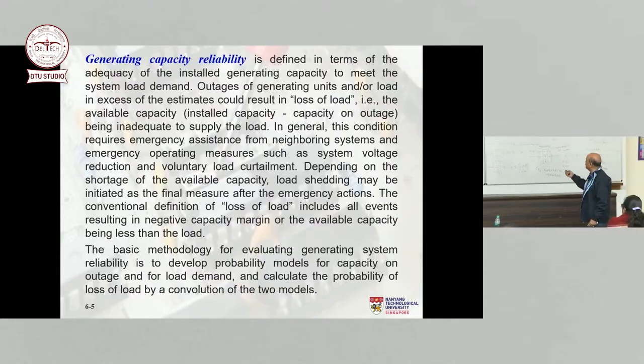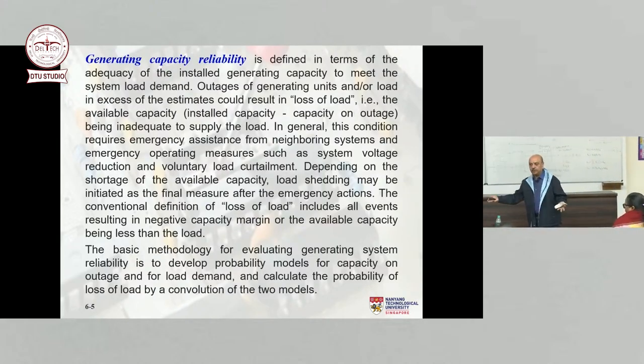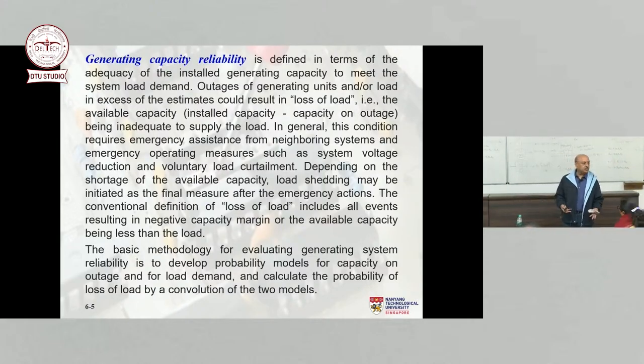But whenever there is a loss of load, then none of this works, because you have exhausted all the possibilities, including willingness to pay and willingness to accept. So the definition of loss of load means you have exhausted all the possibilities, voluntary load curtailment, voltage reductions, interconnection benefits, willingness to accept, willingness to pay, and now you have no choice but to cut the load.